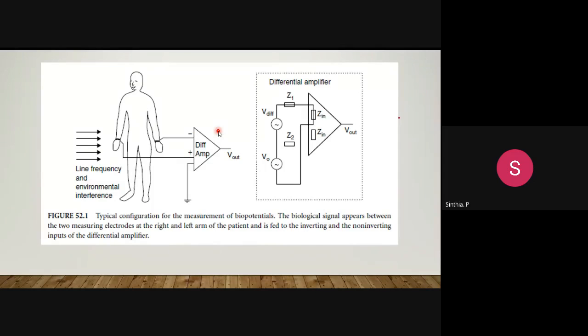Current technology offers differential amplifiers with a voltage noise of less than 10 nanovolt per root hertz. The current noise should be less than 1 picoampere per root hertz. Both parameters are frequency dependent, so they will decrease approximately with the square root of frequency. The exact relationship will depend upon the technology employed in designing the amplifier input stage.